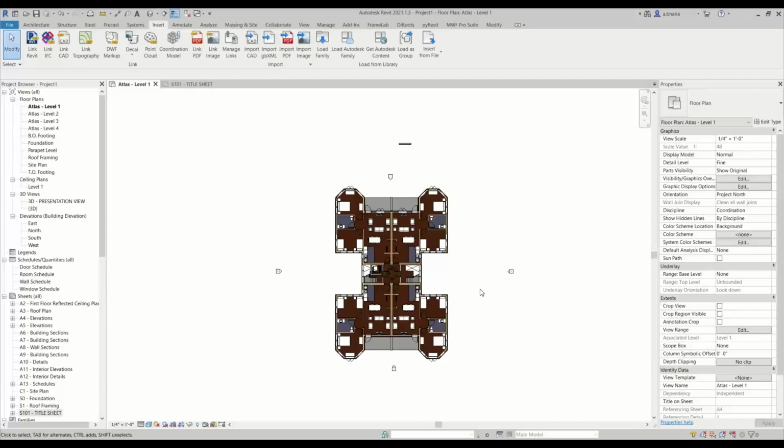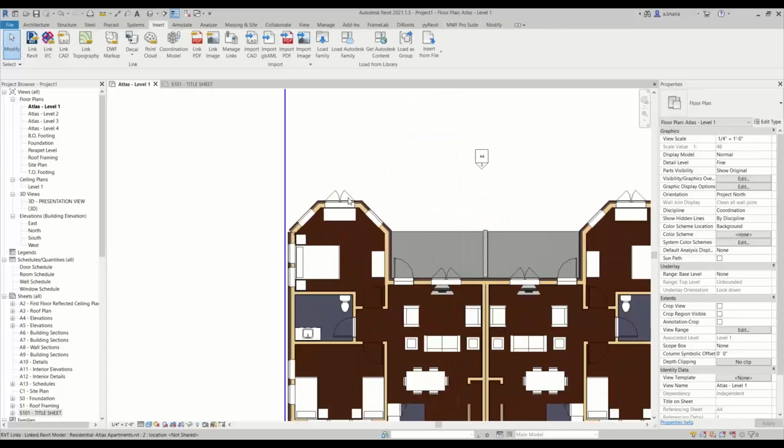we can grab all of their wall types and their walls in their exact locations and replace them with our walls. Okay, so one option would be I would go Copy Monitor, click on the wall, and copy their original wall. I don't really like that option very much because my templates are not set up for their original walls. My templates are set up for my 5-inch, 4-inch, and 6-inch walls, right?